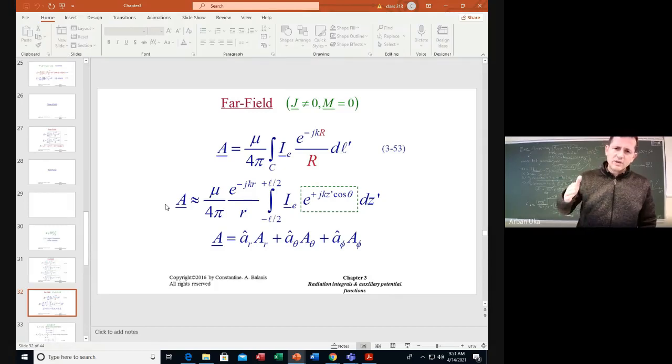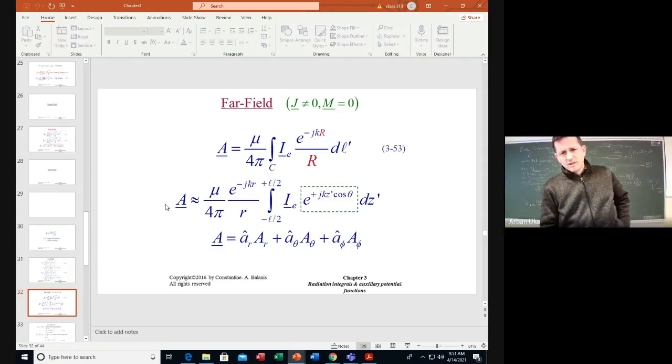The radiating power can be found also in the far field regime, but the reactive power is present only in the near field regime, very close to the antenna. This reactive power is a product of the components which are orthogonal with respect to the direction of propagation of the wave.